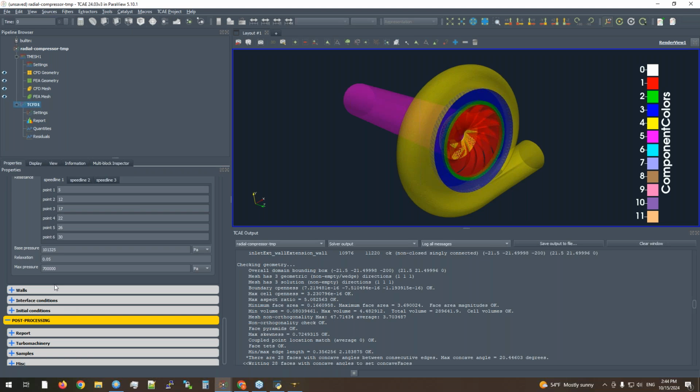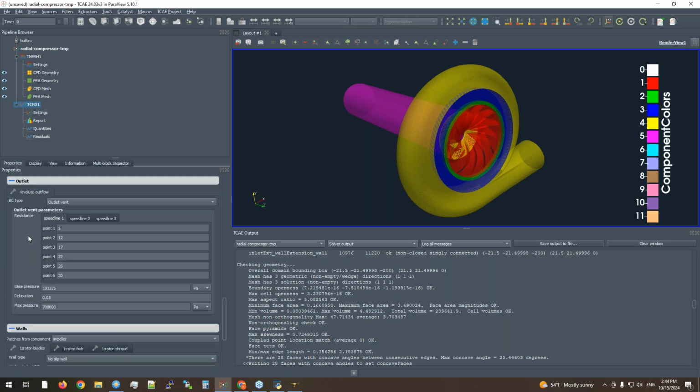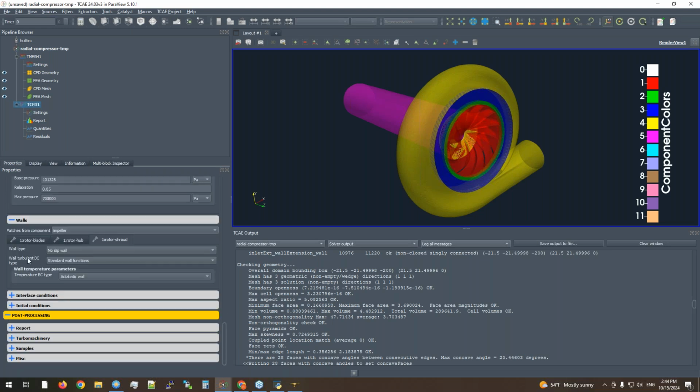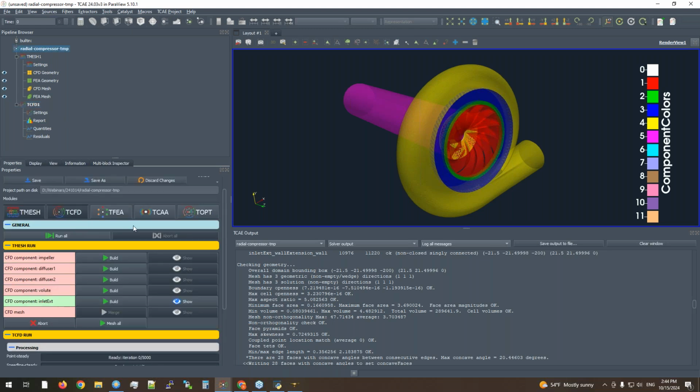And by going through each menu, you will set standard CFD parameters. So I think you can check one of our previous webinars where this was discussed in more detail. And whenever everything is preset, including meshing and CFD simulation, you can hit the Run All button, and everything is run in an automated way.